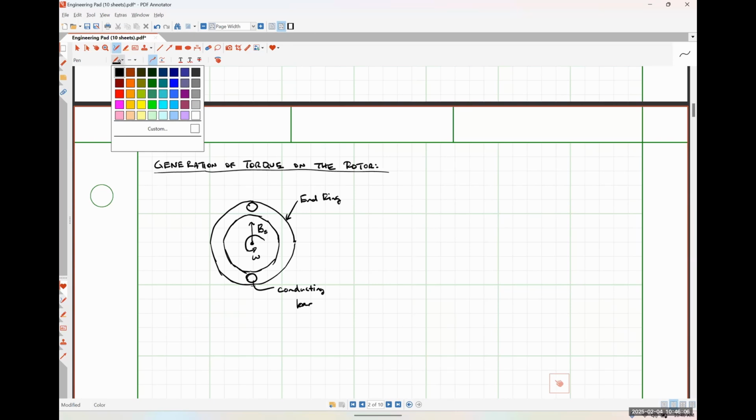If a little bit in time later, our B field is oriented orthogonal to our loop, like we have here where it's perpendicular to the axis that our loop is on, then our flux is going to be at its maximum. Half a turn later, our flux is going to be at its maximum, but in the opposite direction. So we're seeing whenever it's literally in line with our bars, the flux is zero. It goes 90 degrees, our flux hits its maximum, 90 degrees more, our flux is zero, a further 90 degrees, and our flux is at its maximum, but in the opposite direction.